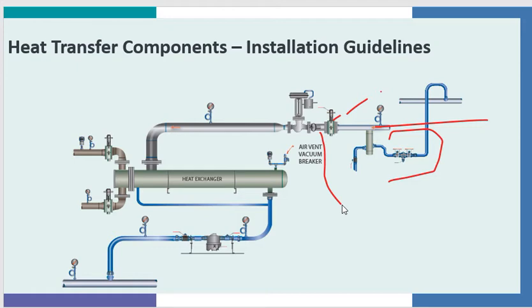The strainer should have a 20 mesh strainer inside. Also always put a blow-off valve on the strainer so the strainer can have PM or blowing down at different times. Next is the steam control valve. And one of the things with the steam control valve is know the turn down of the steam control valve. The other thing is always mount steam control valves in the horizontal plane. And that goes with any isolation valve. Always mount the isolation valves in a horizontal plane, never in the vertical.